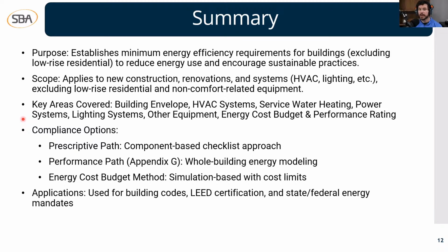Now, let's go over some advice before going over our summary. So some quick advice here. You've got to know your climate zone. It drives many of the envelope and HVAC rules. You also need to start early in the design process when trying to focus on your energy modeling. So you need to coordinate with your MEPs, which is your mechanical, electrical, and plumbing engineers, your architects, and if you have any energy modelers that aren't your engineers, we need to coordinate with them to make sure that we understand what the goals are from an energy standpoint.